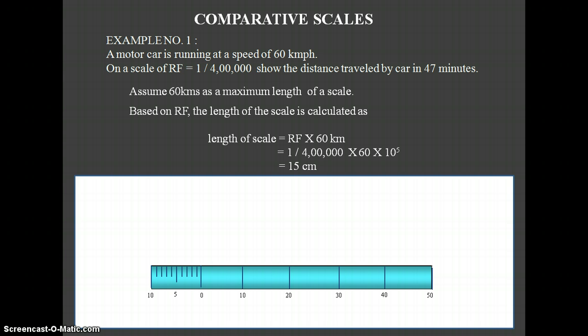So 10 kilometers again. Now construct the minute scale immediately above the kilometer scale we have constructed. Before that, mention the units: main units as kilometers, and the subunits are also in kilometers, tens and ones of the kilometers. Next construct another scale which is in terms of the time, that is minutes. So same, divide into 6 equal parts. Each division, that is the main unit, is equal to 10 minutes.